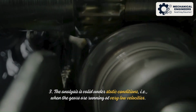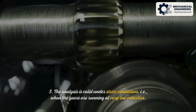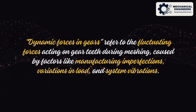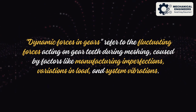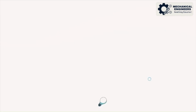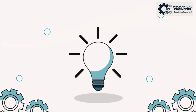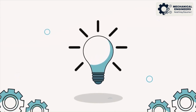Lastly, we base our findings on static conditions, which means we're looking at gears operating at very low velocities. However, in practice, dynamic forces come into play alongside the power transmission forces, but we set those aside for simplicity. These assumptions are crucial for simplifying our calculations, even if they don't capture the full picture of gear interactions.